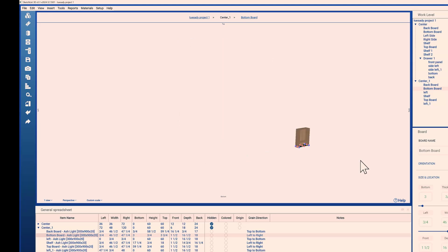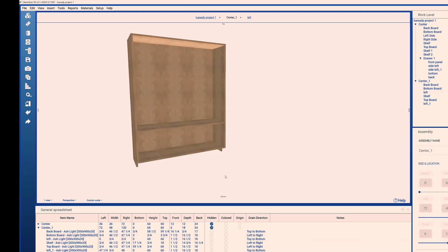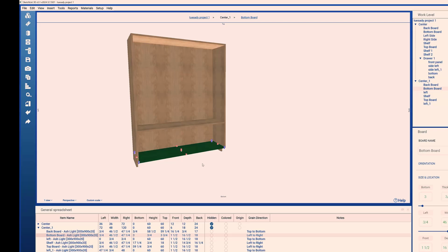Same thing. It's a matter of board detail. So I'm going to grab the board that I want and then take this. Of course, you would figure this out because you're all smart woodworkers. But I'm kind of cruising to cover a lot. When I work, I might put this board up here and clone and space it just to see what it looks like. But before I really get to cloning, I'll completely detail out that board so I don't have to do any more work when I clone it. The same thing here. I would put the dados on this bottom board, and then I would clone that, and all of the boards that I needed would be there.